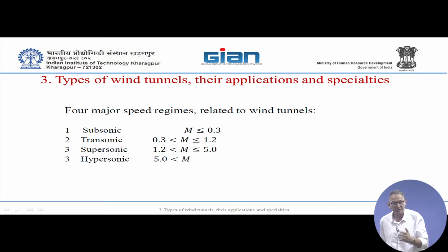So it's roughly around 5. You can run Mach 5 without heating your stagnation conditions. You can run with the standard conditions and expand to Mach 5, and generally you shouldn't liquefy your air. But beyond that, you must heat your flow, so that once it expands, it won't liquefy.